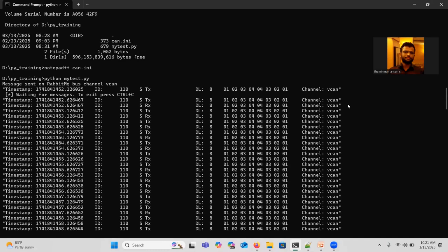That's all. This is the implementation that we have. After successfully achieving this, we started modifying our existing modules, like the BCM module, ICM module, ACC module, all those one by one. We modified all of them. We migrated that code to python-can library based code.